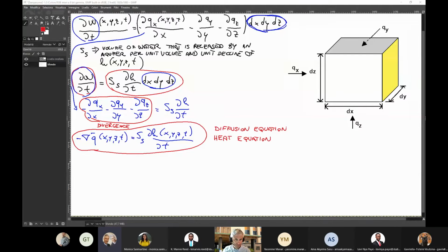Let's write Darcy's law in this form. As I said, it's very simple. We work in 3D. Let me use the color black again. So we can say that Q in the direction X, which depends on the coordinates, is given by minus, I tell you why minus, a constant capital K, which multiplies the change of hydraulic head with respect to X.